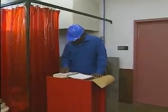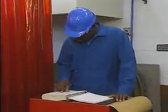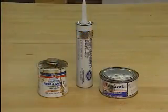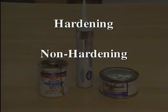When installing new gaskets, the equipment manual for this pump recommends using gasket compound on the sealing surfaces. There are basically two different types of gasket compound. They are hardening and non-hardening compounds. Hardening compounds generally dry to a hard finish and often act as an adhesive to hold a gasket in place on a flange. Non-hardening compounds remain soft or tacky. They can function as a sealant to help fill in imperfections on a sealing surface.